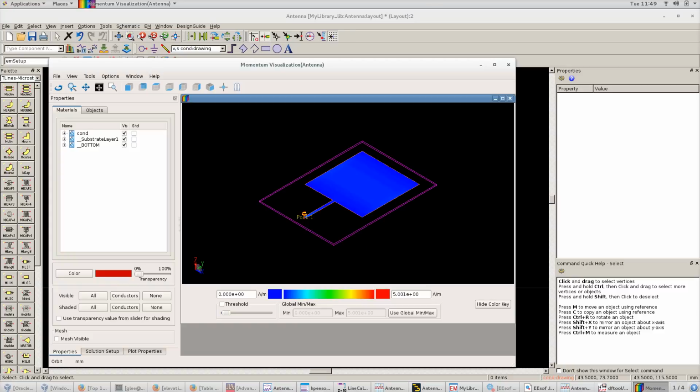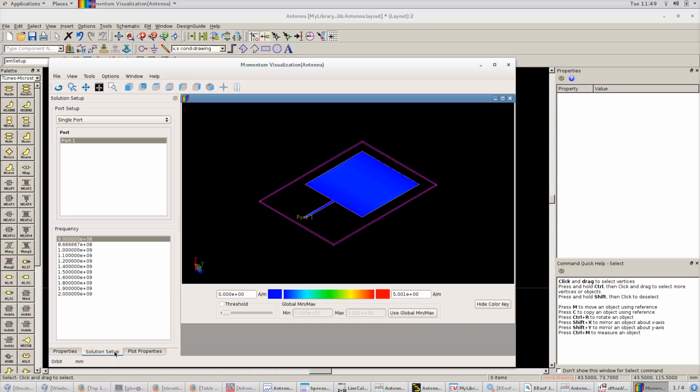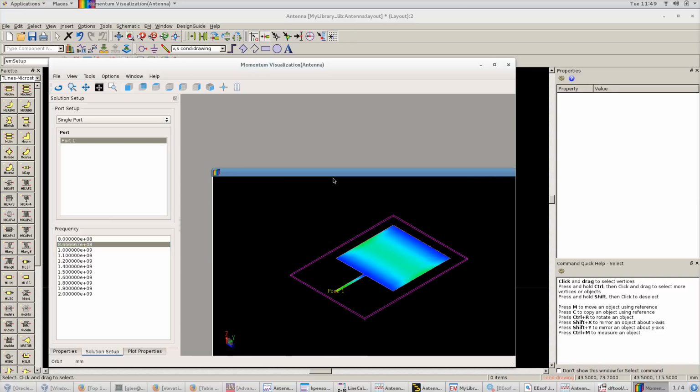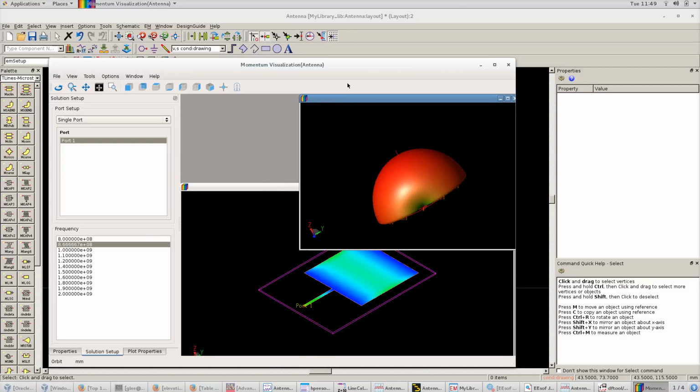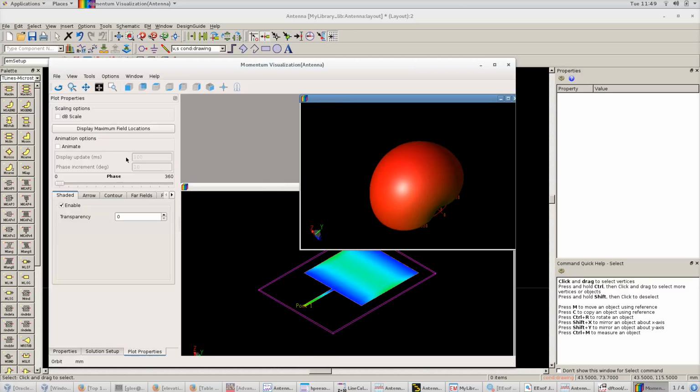It's similar to what you're going to be simulating yourselves, but one thing to pay attention to is you want to set your simulation setup to something that is within the operating range or near one of those resonant points or nulls that you saw in the return loss plot. By doing that, you can actually get a handle on what the actual gain of these antennas might be. You can also think of it this way: if the energy is being reflected from the source, then you're not really doing anything with the structure, and so your values aren't going to be very nice here. Sometimes it's worthwhile to add some additional frequency components that are singular points. That allows you to select a very specific frequency when you do these EM simulations. And I can show you that in just a moment.